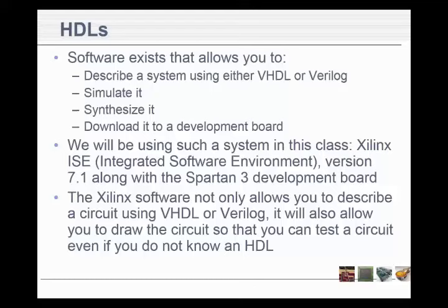Then you're going to download it to a development board, or you're probably just going to use it in some kind of simulator on the machine and see if it works. I think you should always run it through the simulator several times on your computer to see if it works, and then take it down to the board and make it work on the actual board. There still could be some problems there with actual timing issues or something like that.